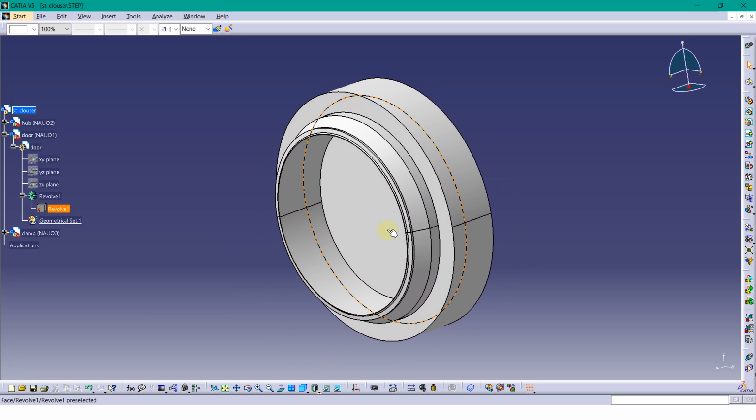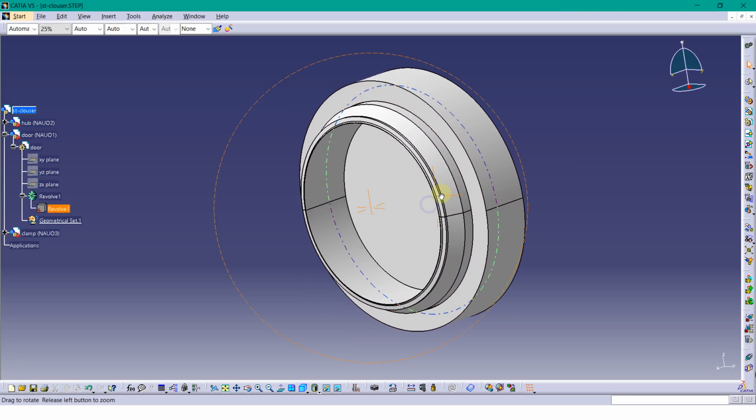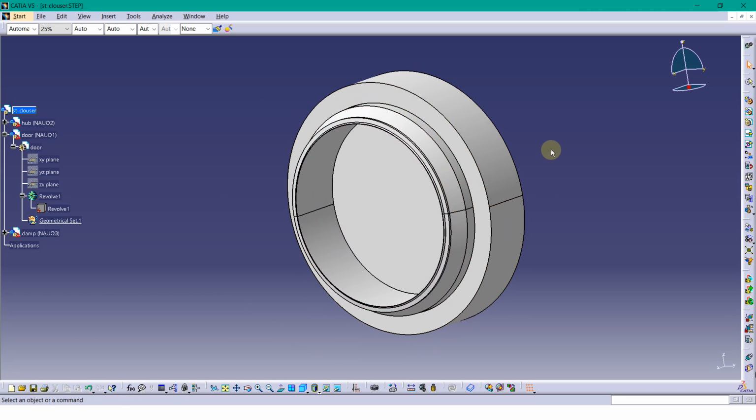Since the problem is axisymmetric, both from loading conditions and the geometry and the boundary conditions, we can simulate this problem by axisymmetric analysis. However, an important result that should be obtained from the axisymmetric analysis is the hoop force inside the clamp part.